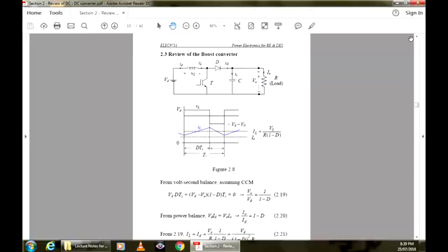So we then do this volt-second balance. That means the rate of rise and rate of fall, having been defined by those equations, the rate of rise is Vd over L and the rate of fall is (Vd minus V0) over L, but the respective times are DTs and (1 minus D)Ts. So if you put the inductor voltage VL equal to 0, that's the volt-second balance equation, and then this would be the output voltage relationship with D. V0 over Vd is 1 divided by (1 minus D).